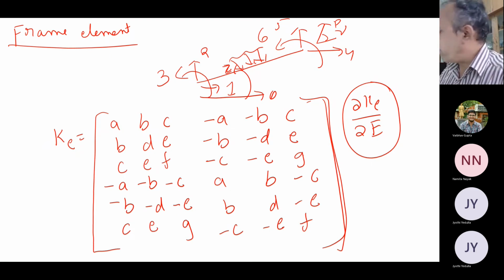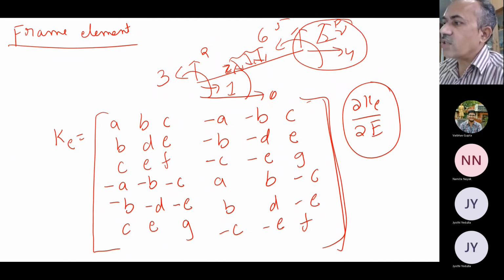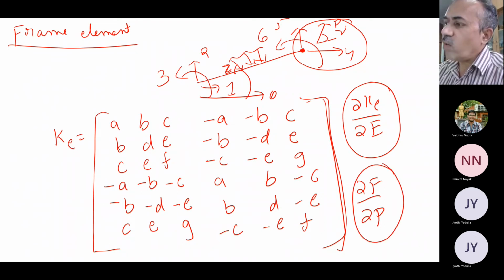See, how do you handle load in FEM? If there is a load here, say P is there, how do you handle the concentrated load in FEM? You will apply it at what point? Apply at nodes. You will apply at the nodal points only. So now if you want to find out derivatives, in this problem let us say this concentrated load P is applied at this particular node. So now you may have to find out dou P also. So now this derivative, what happens?